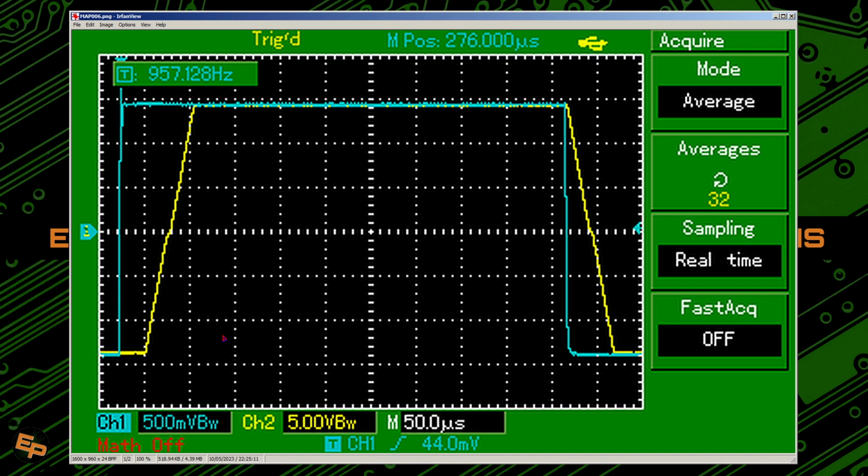If we multiply that by 100, mathematically speaking, on the output we should have had plus minus 150 volts. Of course, that's not possible. First, because I have plus minus 15 volts power rails. Second, because the op-amp would not be able to work with 150 volts anyway.